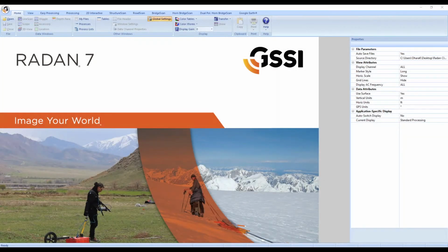We're here at our last day of RADAN training. To recap what we've done so far, we started with a discussion of GPR theory. So we discussed why the image looks the way that it does. We broke it down into scans and samples and discussed what's contained within each sample, the two-way travel time and the amplitude to get to that sample, and how that's represented on the screen.